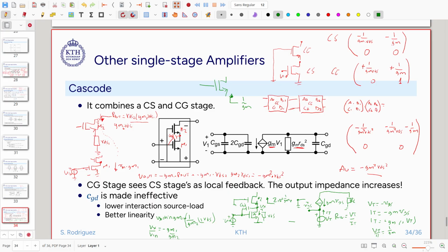Since the transistors are the same, currents are the same, sizes are the same, the transconductances have to be the same, then the gain will be approximately equal to 1 here, if RDS is much larger than 1/GM2, which is normally the case. So from the Miller point of view, this capacitance has only an amplification of 1, a factor of 1.